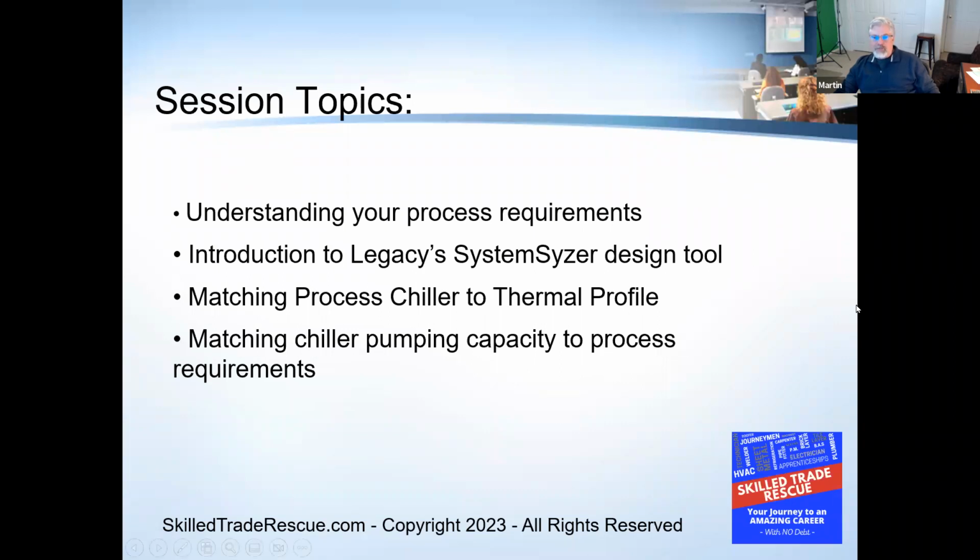And that's actually probably one of the biggest problems we had as a manufacturer, especially when you're doing change outs on a chiller. You're going to ask questions, and hopefully we'll talk about this some more, but you're going to hopefully ask questions about specifications on the existing pump, right? Because not all pump curves are the same. A 1/2 horsepower pump on a Gould's pump is going to be different than a B&G, right? And then you get into the whole subject of impellers being modified, all kinds of stuff like that.